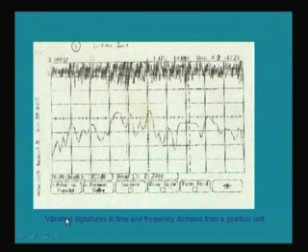So first one is generally in the oscilloscope. You will find that the upper one, especially this one, is a time domain signal. You can see that it's very erratic. Nothing you can make out from this. And the lower one is the FFT of the above time signal, so this is the frequency domain signal. You can see that it has some peaks, that is the vibration amplitude at these frequencies. Some of the frequencies are very high, so these are of our concern.